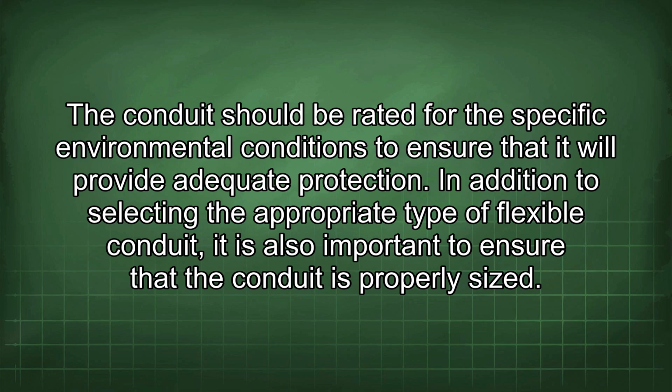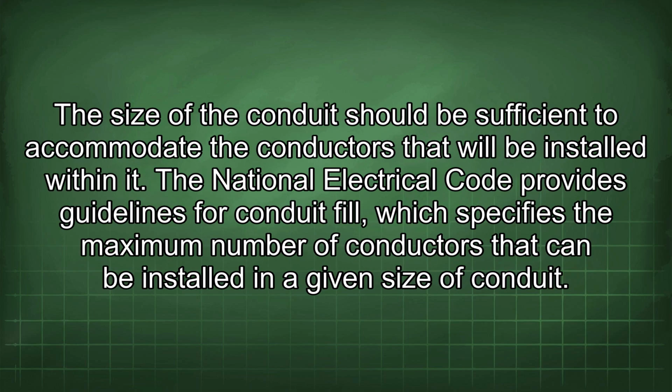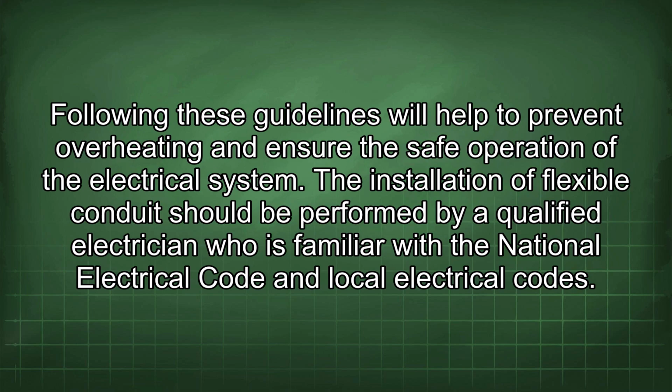In addition to selecting the appropriate type of flexible conduit, it is also important to ensure that the conduit is properly sized. The size of the conduit should be sufficient to accommodate the conductors that will be installed within it. The National Electrical Code provides guidelines for conduit fill, which specifies the maximum number of conductors that can be installed in a given size of conduit. Following these guidelines will help to prevent overheating and ensure the safe operation of the electrical system.